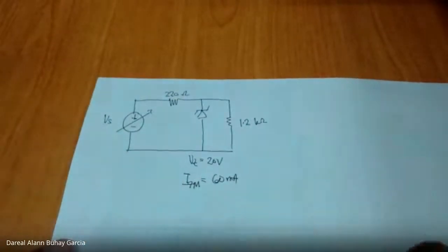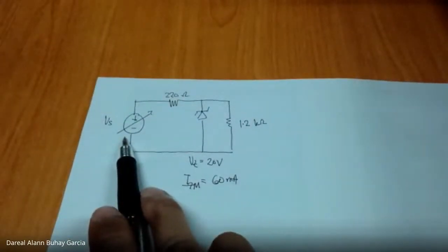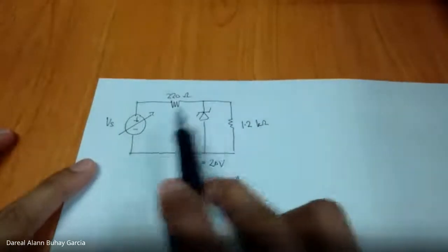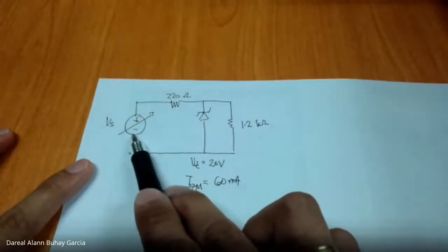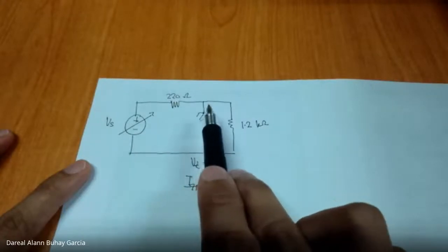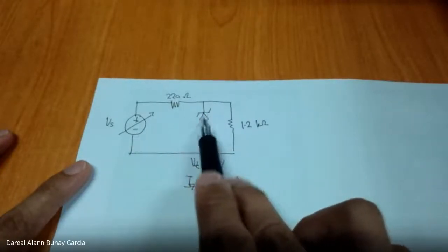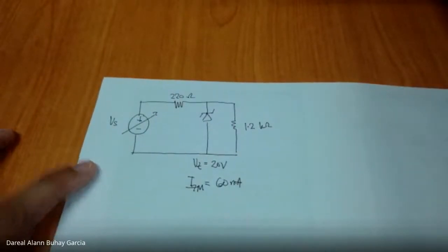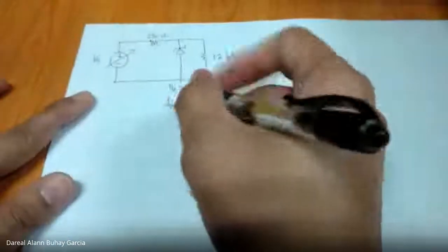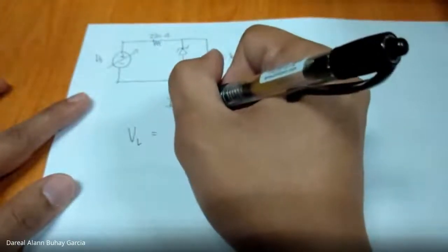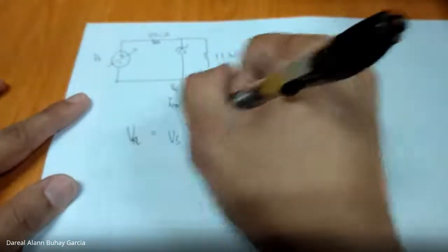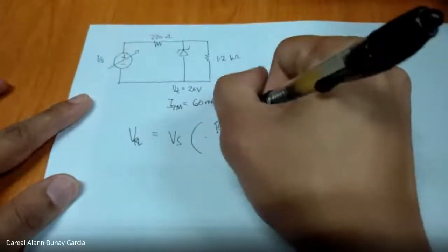Okay. So, question. What value of the source will turn on the Zener? The same as earlier. What should be the value of our VS? Enough to turn on the Zener diode and just enough that it will not be destroyed. The same formula applies: the formula for our voltage divider, VRL to VS, RL.